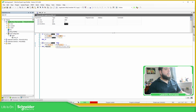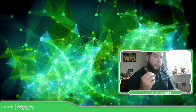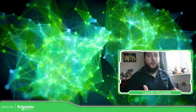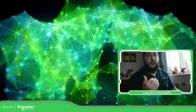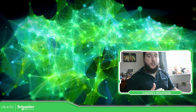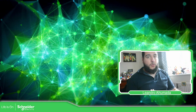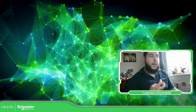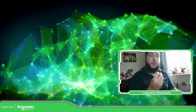So this is basically how you unforce a value. You need to pay attention to how you execute the code, because the force will write at the beginning of each cycle, and not in the complete code that you have. So probably if you analyze everything with the force, you may have different behaviors than you expected when comparing with the visualization.